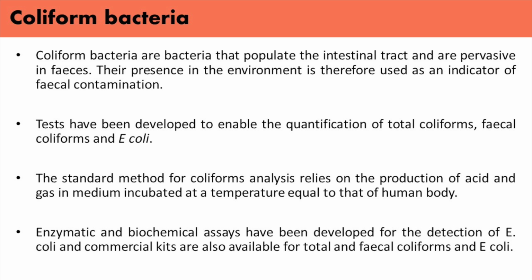However, there are complicating factors, such as bacteria from the genus Escherichia that can grow in the environment, and the test is therefore not 100% indicative of fecal contamination. Tests have been developed to enable the quantification of total coliform, fecal coliform and E. coli.